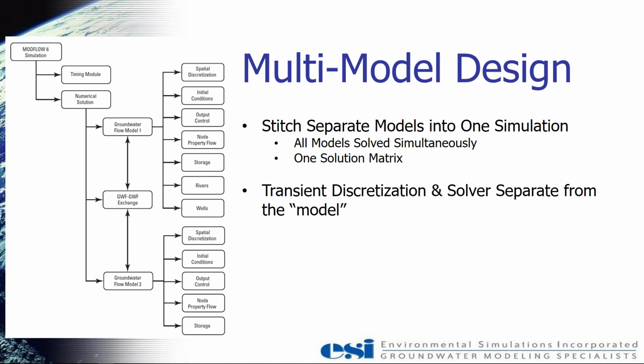One thing that's very new in MODFLOW6 is the idea that you can take multiple independent models and stitch them together into one simulation. This is similar, for those of you that know a lot about the various versions of MODFLOW, to a version called MODFLOW LGR, which stands for Local Grid Refinement.